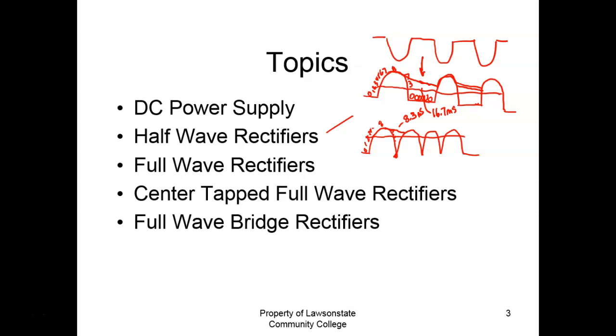So these we call full wave, and we have two types that we'll cover, called a full wave center tap, and then we have a full wave bridge. The half waves, you can see in a minute why it's so cheap. And I've got to get my camera working to show y'all this. Full wave would get a higher average voltage out of it.